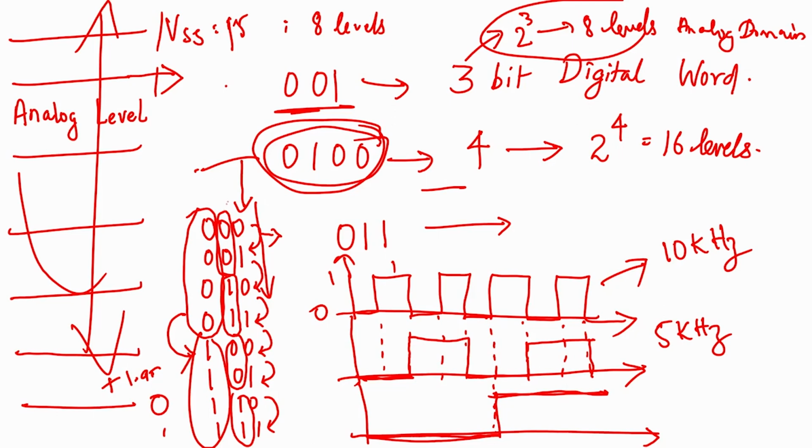Now, what these bits stand for is the information as to the level changes that happen right here. Each level change happens here, no. So, each bit is like having an information about these finer changes, okay. So, this last bit, right. That last bit kind of tries to tell you that, okay, this is a major shift that happens, okay, and then these are finer additions to your voltage.